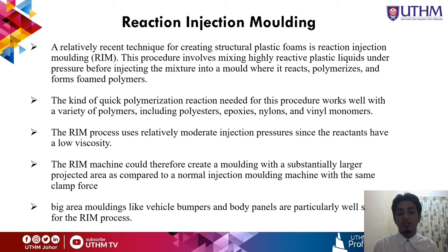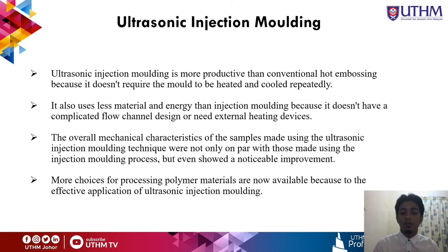The process uses relatively moderate injection pressure since the reactants have a low viscosity. The machine could therefore create a molding with a substantially larger projected area as compared to a normal injection molding machine with the same clamp force. Next is ultrasonic injection molding.